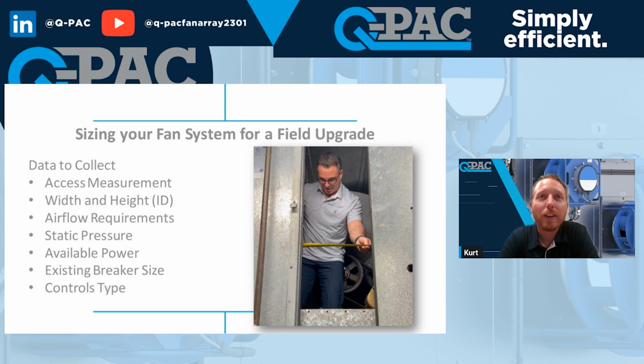Nobody's going to get fired for oversizing one of these fan systems, but you may get fired or get in trouble for undersizing. You're going to have bigger issues, right? So everybody adds an inch or 2 inches of static pressure, and it just adds up. So do a TMB, save your customer some money, get the right size unit in there, and just do your homework and understand the real requirements of that system.